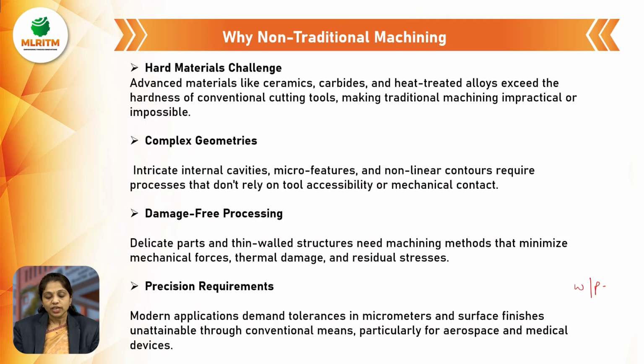Another is damage-free processing, because in non-traditional machining there is no contact between the tool and the workpiece. Delicate parts or thin-walled structures need machining methods that minimize mechanical forces, thermal damage, and residual stresses. The next major challenge is precision requirements. Modern applications demand tolerances at micro levels and surface finishes unattainable through conventional means, particularly for aerospace and mechanical devices.